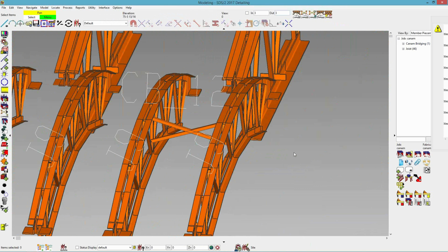So that concludes today's webinar on the new Joist member. We have now covered the merge of the BIM joist and the system joist into a new hybrid joist member. It now has the ability of the connection design that the system joist had, along with the customization and solids of the BIM joist. We now have a new setup for the joist, auto standard connections, along with new erection view detailing options.